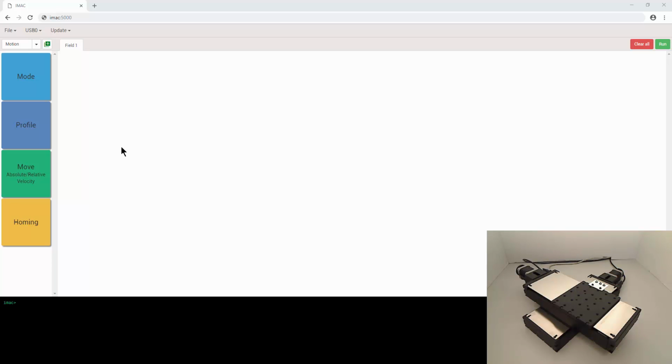The array block allows the user to create a state machine and automate sequencing through elements of the array as coordinate points and I/O states. In this example, I will show how the array block can be used in applications like pick-and-place assembly, pipetting in lab automation, and others.